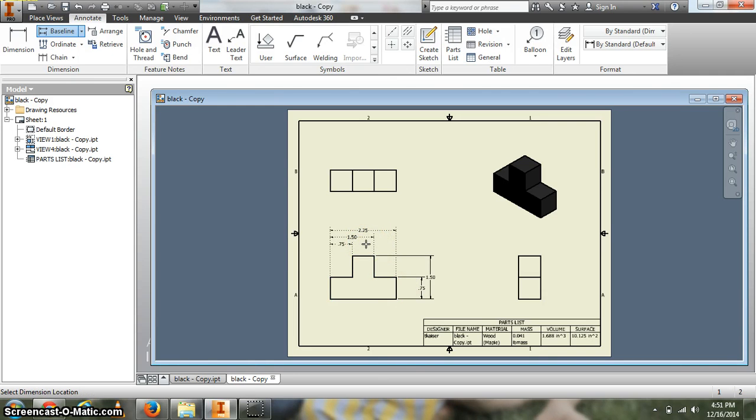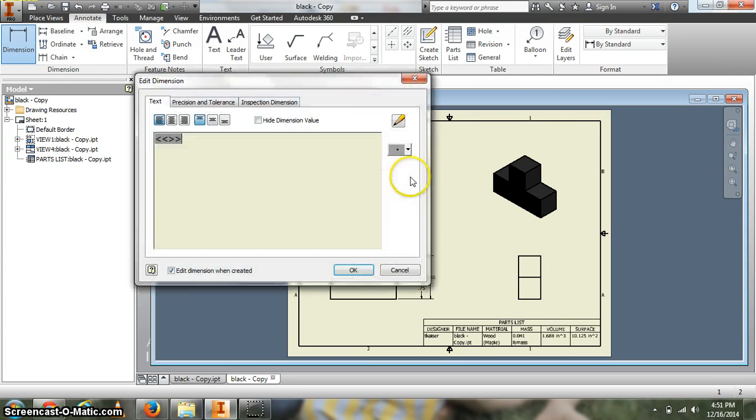Continue, drag them up, and that's basically all the information that we're going to need for that front view. Last one we'll add in there is a single dimension. Oops, I lost that one. Create. Single dimension showing thickness or depth of part.